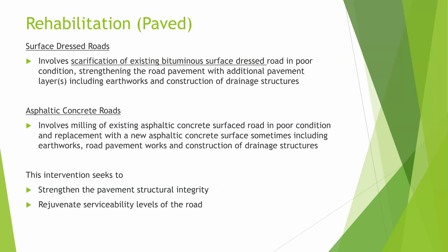Now, for asphalt concrete roads, under the rehabilitation on paved roads, you mill the existing asphalt concrete surface in poor condition and replace it with a new asphalt concrete surface, sometimes including earthworks, road pavement works, and the construction of drainage structures. Later, I'll show some pictures requiring some rehabilitation works and overlay works as we go along. Now, the intervention here for rehabilitation on paved roads is to strengthen the pavement structural integrity and also rejuvenate the serviceability levels of the road.